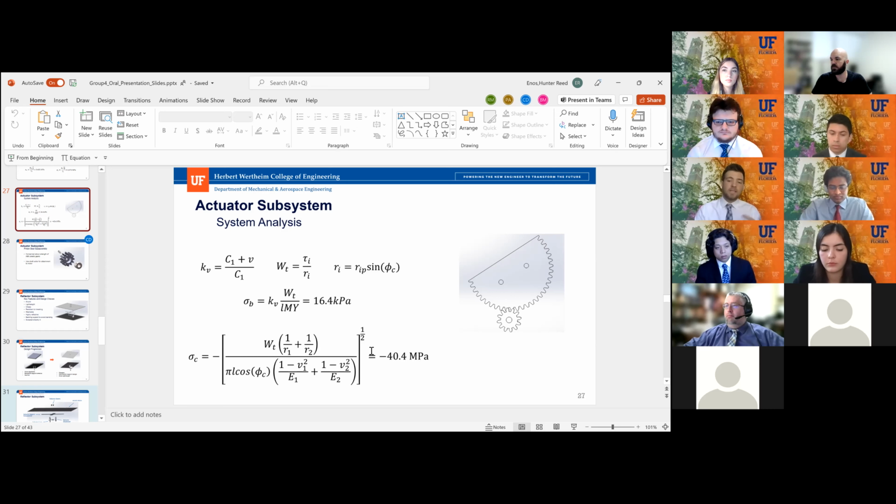Now, over time, those effects are going to build up. It's going to slowly wear. But one of the things to keep in mind is that, in contrast to normal application of gears, these are moving extremely slowly and only come into contact twice. Every one of the teeth comes into contact only twice a day, because it would move throughout the day and then have to reset at night. And so that's one of the things: this K_v velocity factor, velocity being 0, cancels. You're going to have probably a similar effect with the wear, in that it's going through such a minimal number of cycles that we can expect a long lifetime.